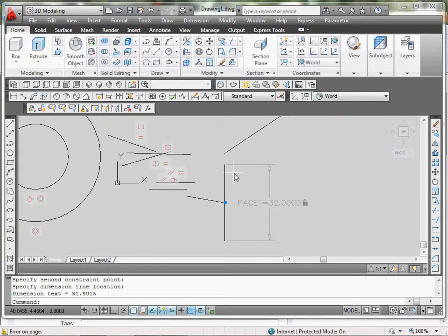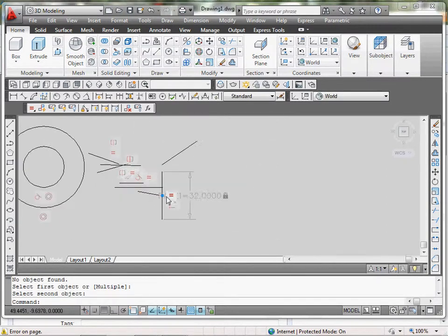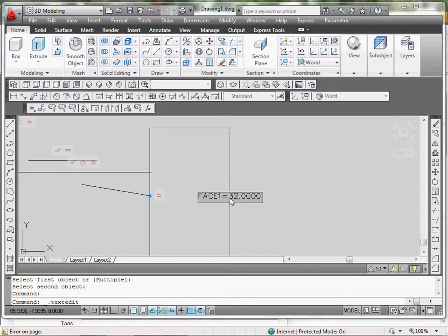It actually readjusts it to that specified amount, and if that's parallel or equal to another line, it's going to change the other line also. So if I make, where's equal? This line equal to this, you can see if I change this again to, let's say, a really small number, like 2.